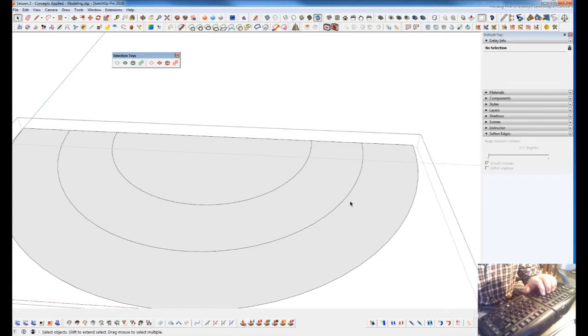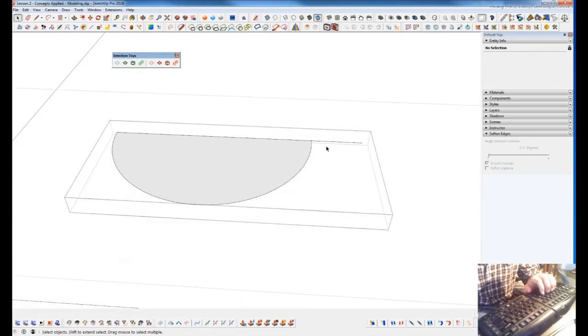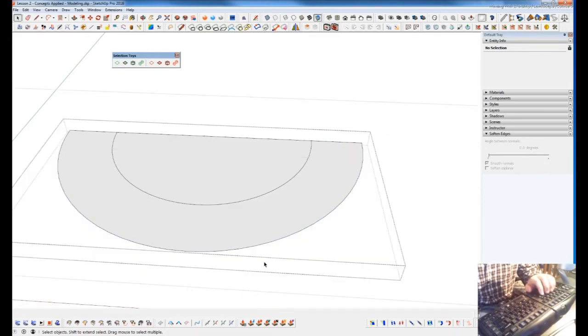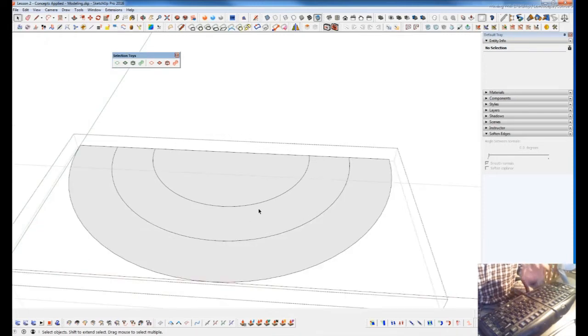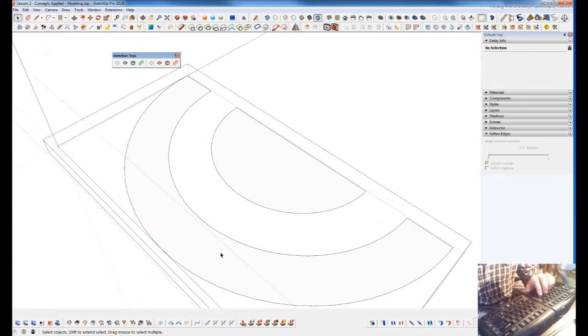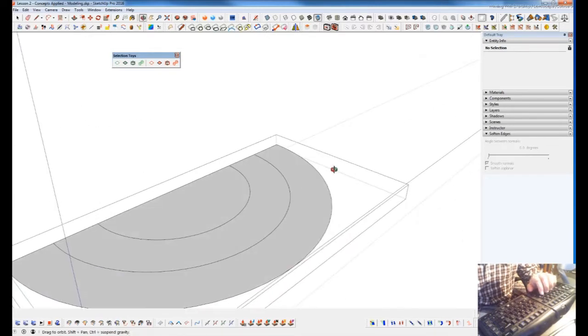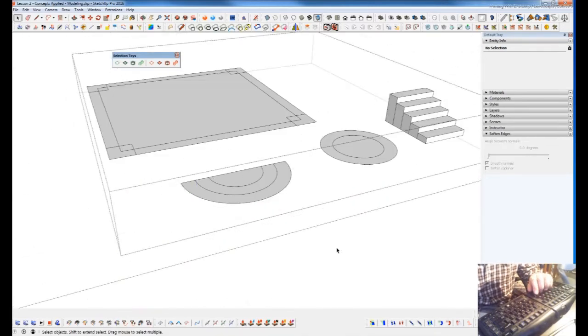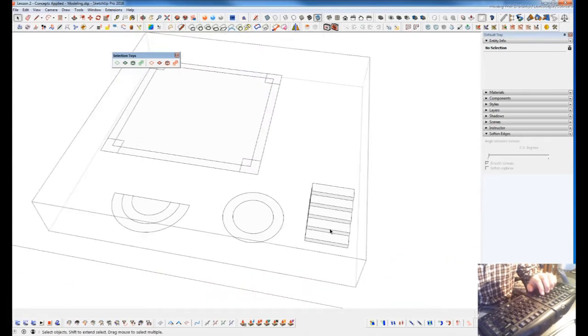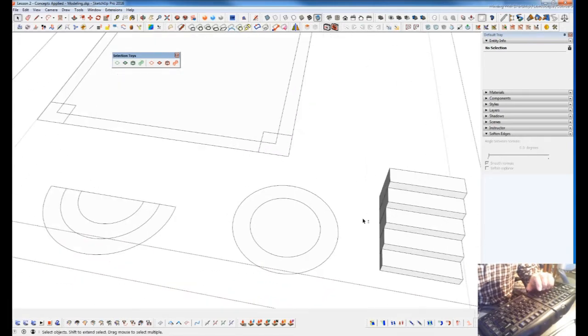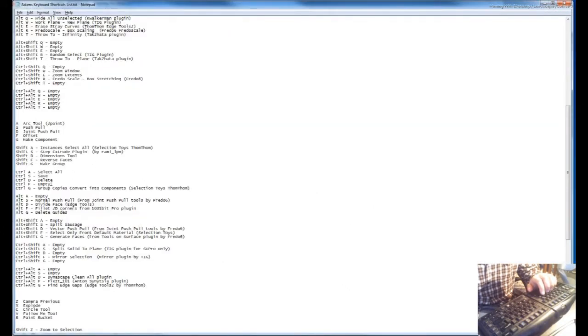And again, making a group creates a second set of edges that supports both attaching faces. So it'll recreate the edge that's here and leave it so it supports this. Instead of deleting this, which got rid of the edge which supported that face, now group it, delete it. Now everything else stays intact. And that's something you need, not even an option. Get that down. Remember that. Group, delete. You'll need that. It helps so much when it comes to cleaning things up and prepping your 2D stuff. And then when you get into modeling, it's something that you need to commit to memory, and it needs to be second nature.